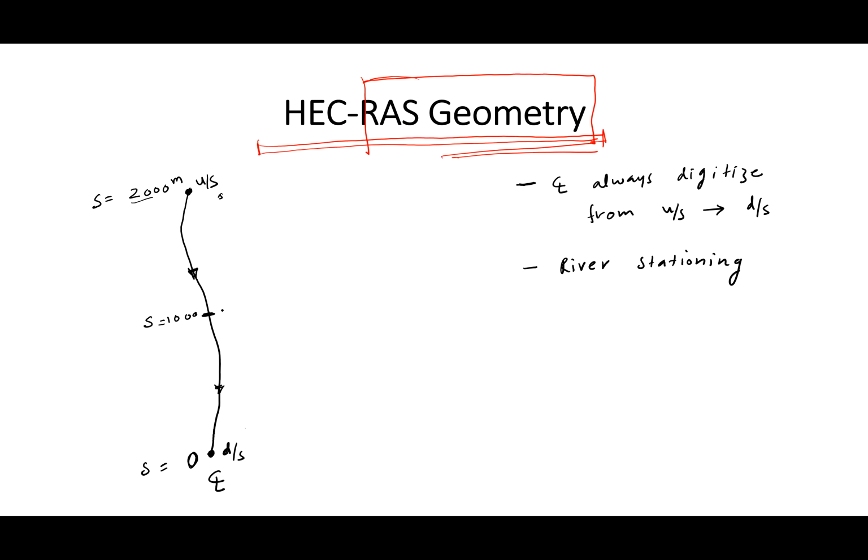If it is not georeferenced, then we'll see what happens when we do our HEC-RAS lab. So this is something I want you to remember, reverse stationing. This is our first thing we have to define when we create a HEC-RAS geometry.